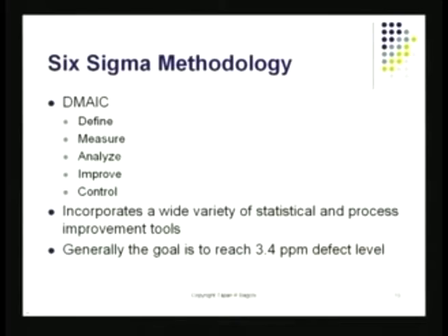So, let us get back to the slide here again. Notice here, I defined what the issue was, I made some measurements, then I did some analysis, I might have used the cause and effect diagram, then I do improvement when I am using DOE and perhaps some other statistical methods, then I do control, which is like when I find the optimum setting for those different variables and I start controlling the process to be there. And one easy way to do that is to apply SPC at the input stage also. If I do this, of course, I may actually have to utilize some other statistical tools also. The result is generally that you reach the defect level of parts per million.